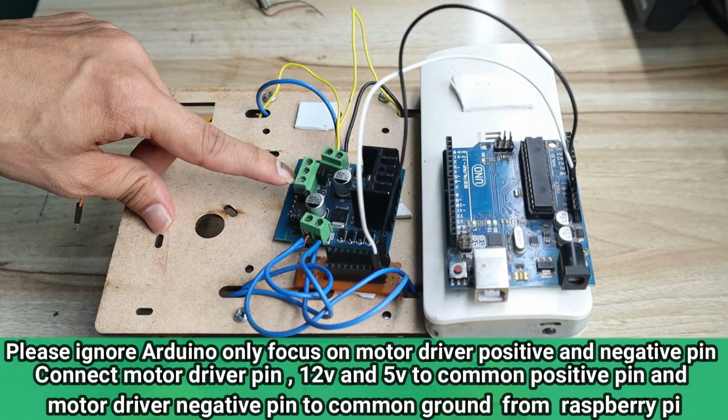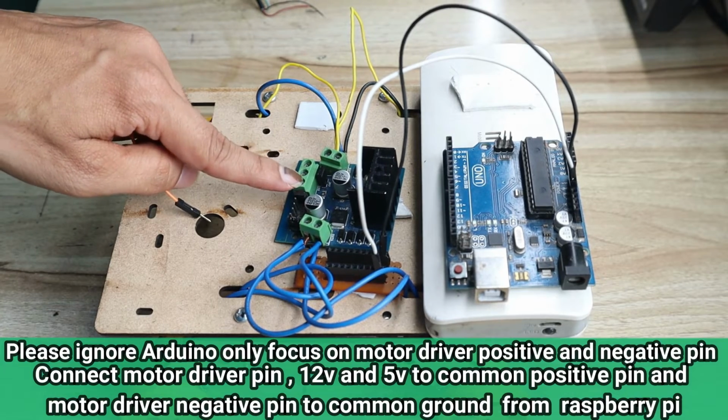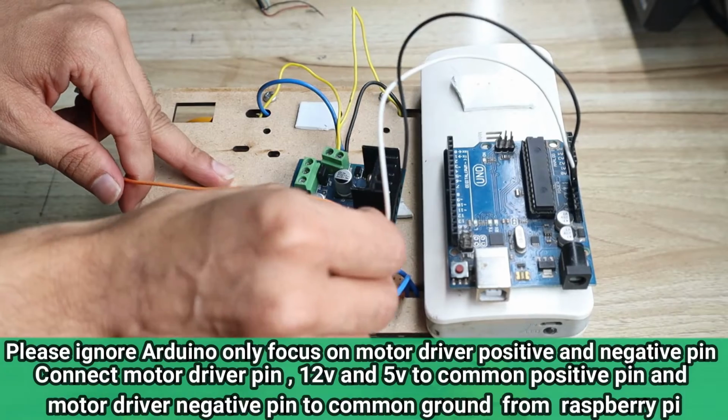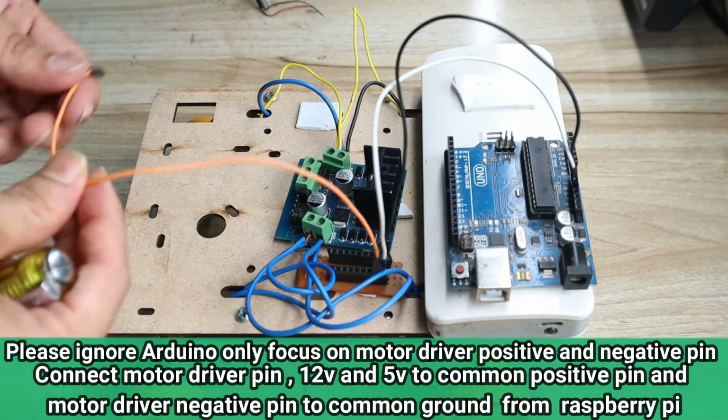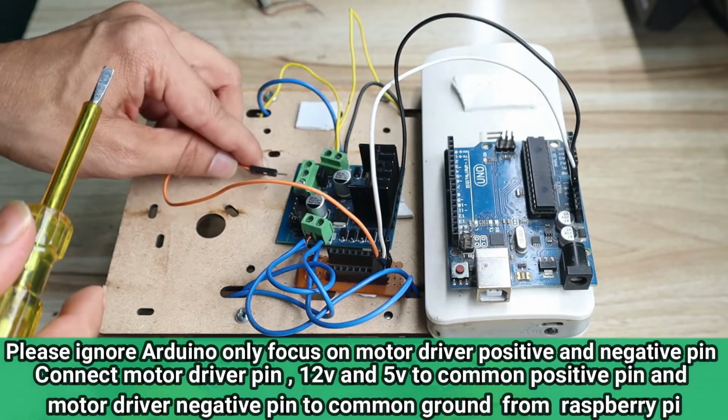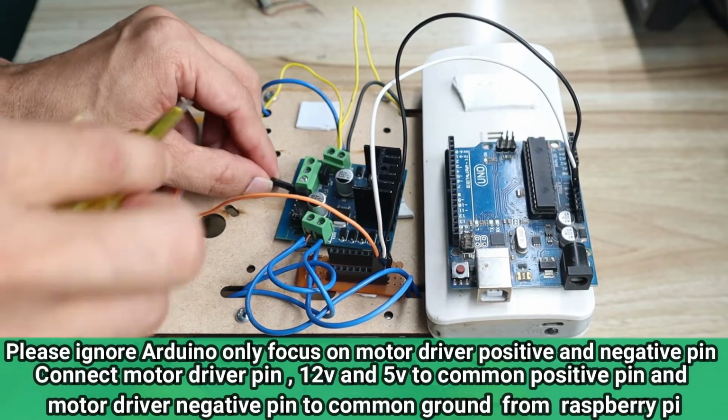Now the L293D motor driver IC has one 5 volt supply. So take the positive pin from the common pin, and connect that to the 5 volt supply here. Okay, so this is the 5 volt supply. I will connect just here.